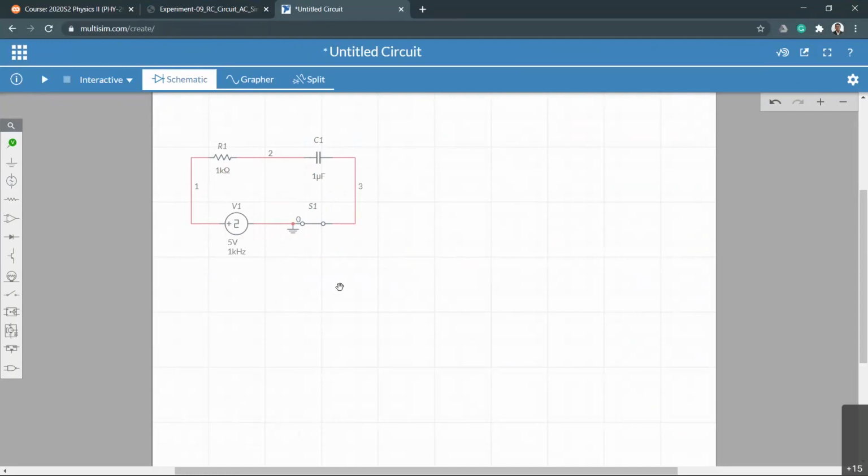Now, one important thing: technically you can apply any numbers. It doesn't matter what the capacitance value or the resistance value is. However, with this RC circuit, it's very difficult to observe the charging and discharging curves using the oscilloscope unless you have properly fine-tuned values for the resistor and capacitor, because these depend on the given input frequency, right?